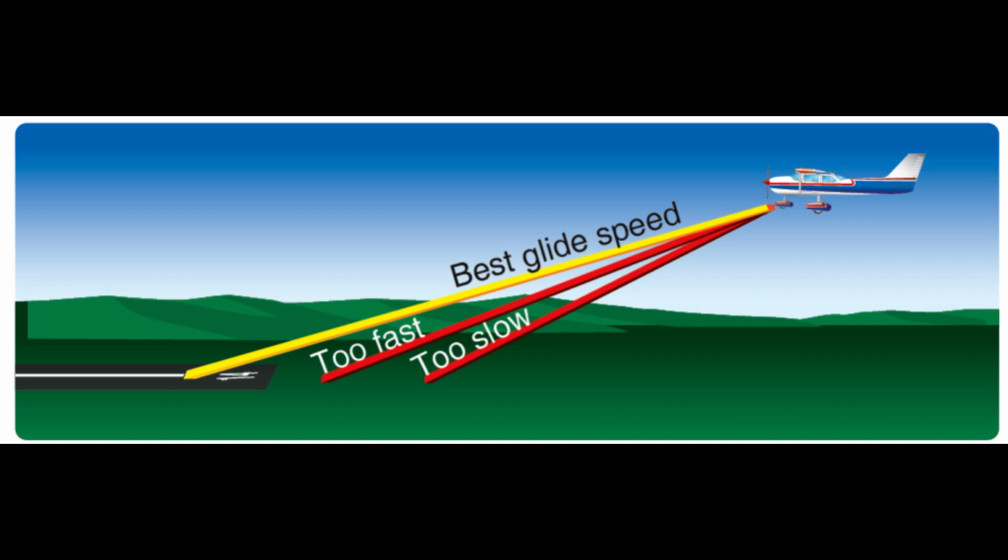During powered operations, the airplane design compensates for the effects of P-factor and propeller slipstream. While these effects disappear during a glide, the design compensation remains. During glides, it is likely that slight left rudder pressure will be required to maintain coordinated flight. In addition, the pilot needs to use greater deflection of the flight controls due to the relatively slow airflow over the control surfaces.